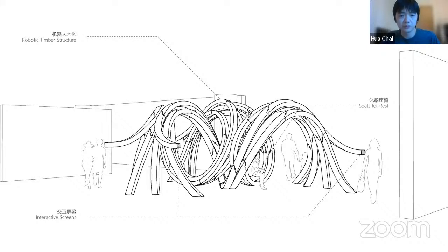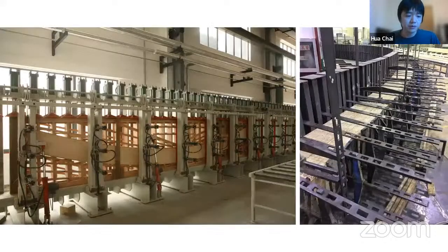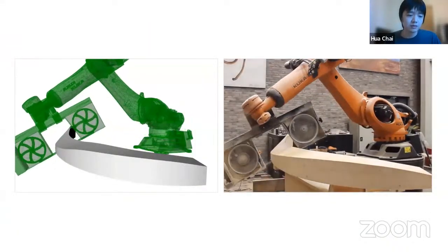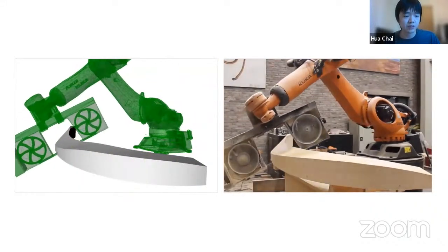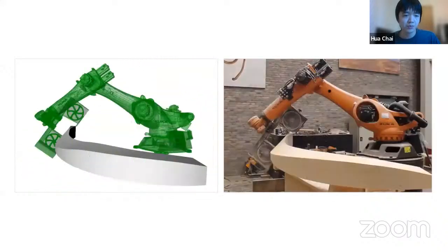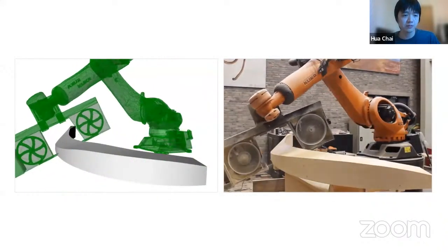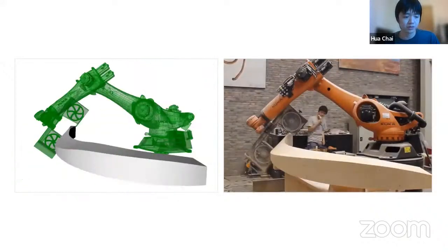So all the beams are double curved with torsion. While the straight and single curved beams can be produced with current technology in the factory, there is still no efficient way to produce the double curved ones. But the robotic bandsaw cutting technique, which can cut the ruled surface with high efficiency and accuracy, has been proved to be one feasible solution for this double curved glue-lam production.